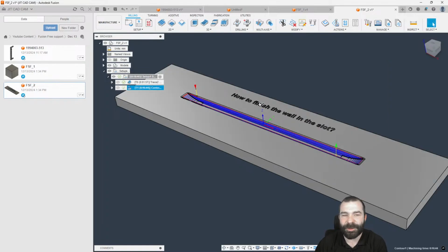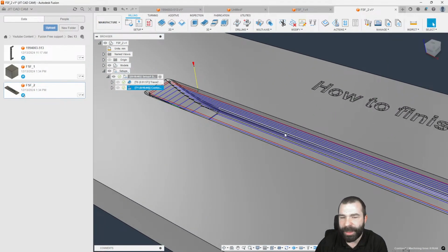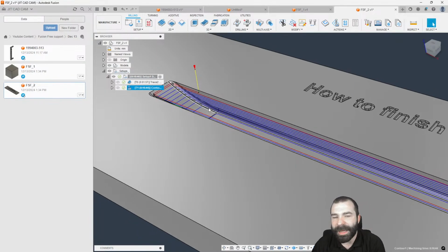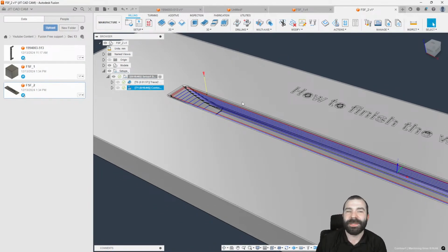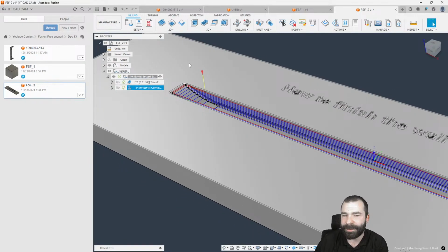And as you're going to see, we're now going to use a 3D toolpath to run around the inside of this part and again create that fillet. More step downs, the better, of course. But I think that gives you a little different approach, by using a 3D toolpath to accomplish that same kind of task, right?